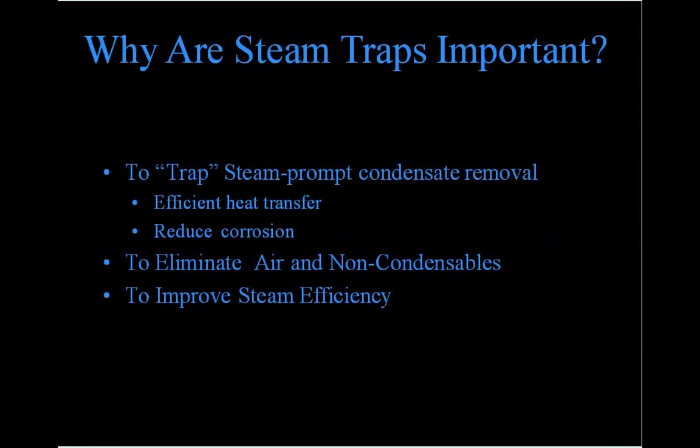Why are steam traps important? Obviously, you want to get any liquid out as quickly as possible because that's going to impact the amount of heat transfer that you might have, and also getting the liquid out of your pipes, your vessels, your heat exchangers will also help reduce any corrosion that the liquid might have or might cause within those systems.